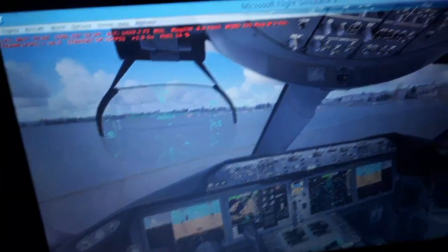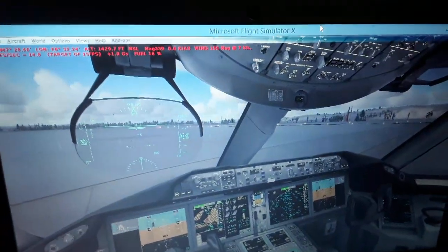They transmit the radio frequency that is received by the onboard antennas of the aircraft and can help us align with the horizontal localizer and the vertical glide slope. You can see the ILS localizer displayed in the primary flight display. We have to tune each runway's own radio frequency, and we're also going to use the magnetic heading of 136 degrees for this runway, runway 14 at Zurich International Airport, LSZH, in Switzerland.